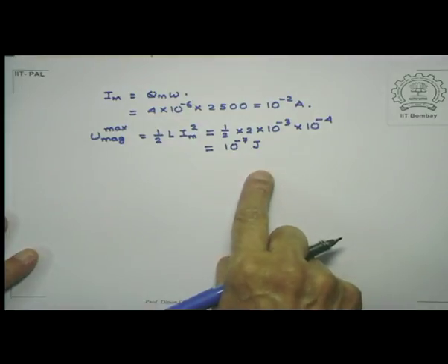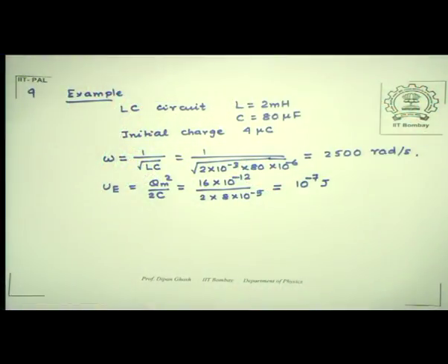I said as expected because obviously at this time all the energy stored in the capacitor has got converted into the magnetic energy associated with the inductance, and this push and pull mechanism where electrical energy gets converted to the magnetic energy and vice versa continues as long as the oscillation persists. So this is about an oscillating circuit, and the only point to realize is that what we have assumed is slightly unphysical, because we have said there is no resistance in the circuit. But then if there were resistance in the circuit, this will lead to damping of these oscillations, just the way the friction would lead to damping in the mechanical circuit.